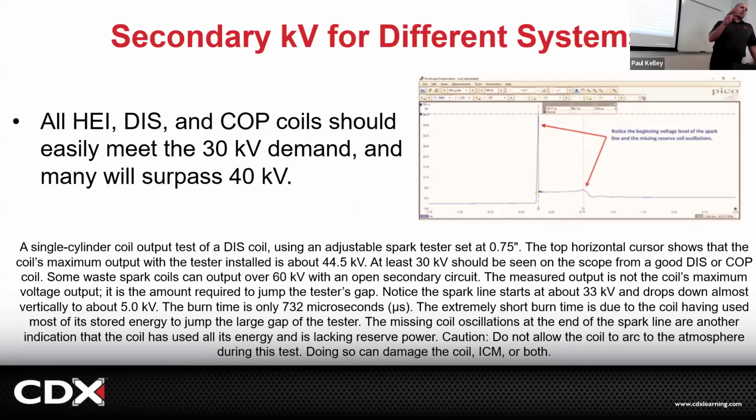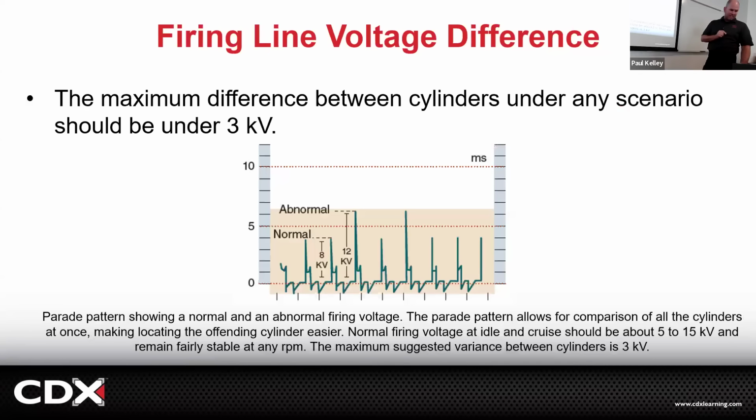So you're going to take this as a basic lesson. And if you really are testing a specific vehicle, you may have to reference service information to get the exact waveform it should have. Don't assume that because your waveform doesn't look like this, it's bad. Not every waveform is the same depending on the coil design and the system design. But we'll still discuss it as a baseline.